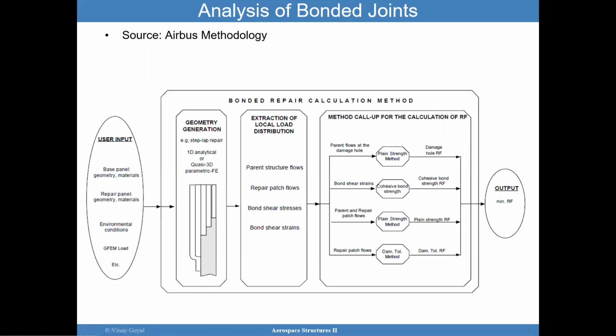The Airbus methodology for bonded repairs is very similar. You're really looking at the repair, bonded shear stresses, bonded shear strain, similar to the bonded joint lecture that we talked about, is in essence what we're doing here. So feel free to pause the video and take a look at this Airbus methodology.